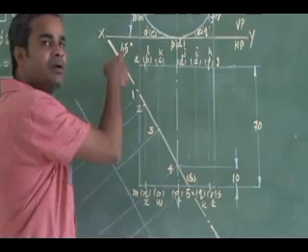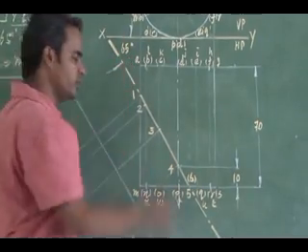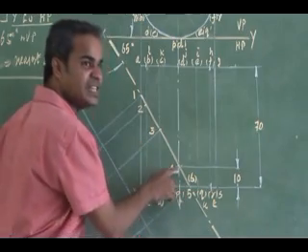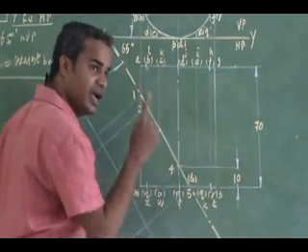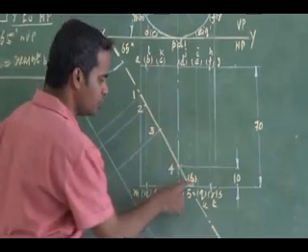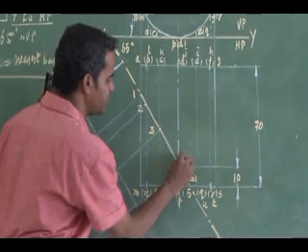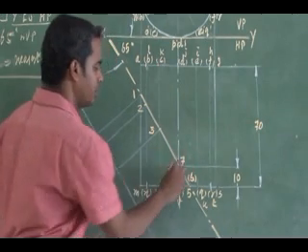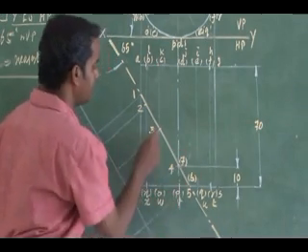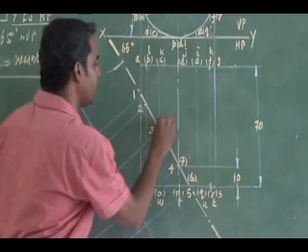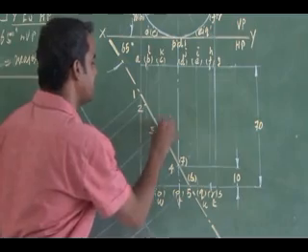Then you come back in the same manner along the cutting plane, searching for hidden cutting points on hidden generators. So after 6, I have immediately here a hidden generator PG, that is my cutting point 7, that is hidden. Then here I will have another hidden generator OC, that is my cutting point 8, which is hidden.